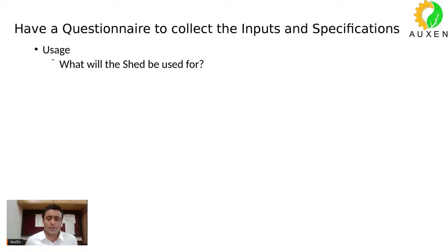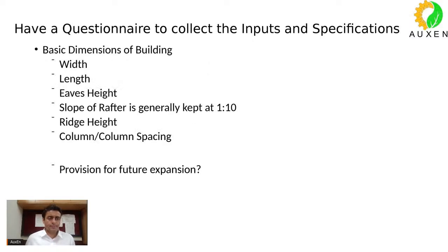Of course, I need not stress on this point more. We all understand the importance of understanding the usage of your structure. Here I am talking more about the industrial shed. So understanding usage of your shed is quite important. So always ask what this shed will be used for. Understand the basic dimensions, the width, the length, the eaves height, the slope, roof slope.